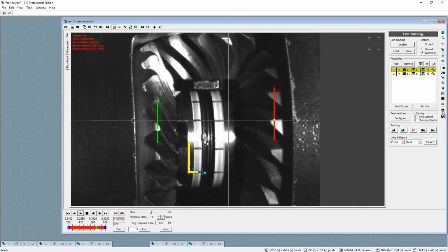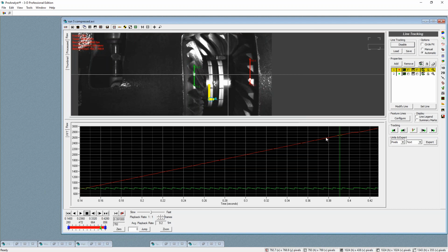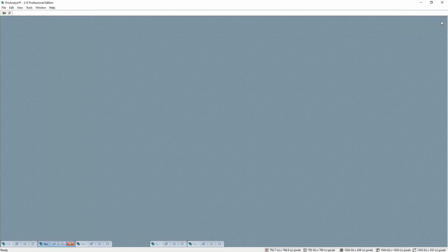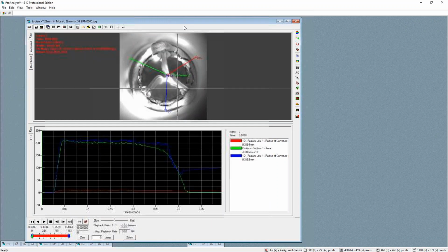So when we look at a graph, I can very quickly and easily see one of these is an unwrapped angle version of this, and the other one is just the progression of the motor itself. So this is giving us the frequency of the rotation of the motor. And then we can compare that to the vibration that we're measuring in our 2D systems as well.